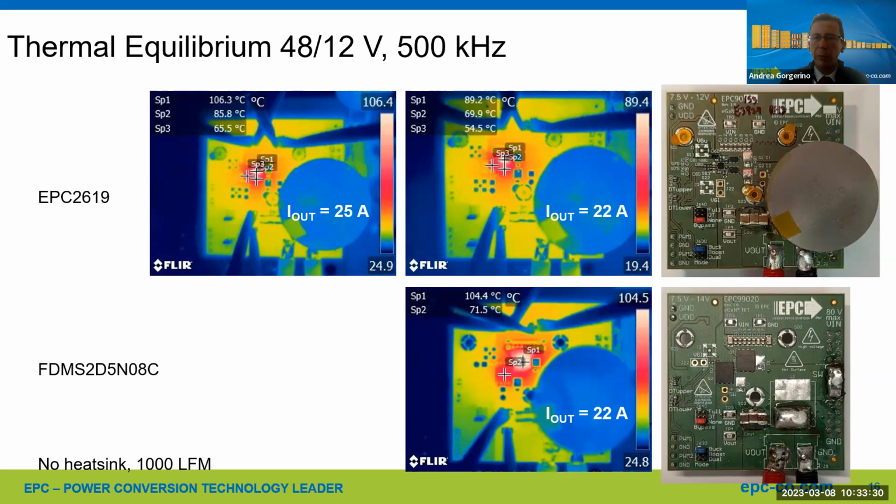They have, for example, still an exposed top, so that still allows you to take full advantage of the topside cooling that we offer on our devices. So that's also a very interesting alternative to our chip level scale packages. They allow for a little bit better clearances on the bottom, so the manufacturability is better. So we have a growing line of products that are released and that are in development in this QFN family also, which I have not shown today.